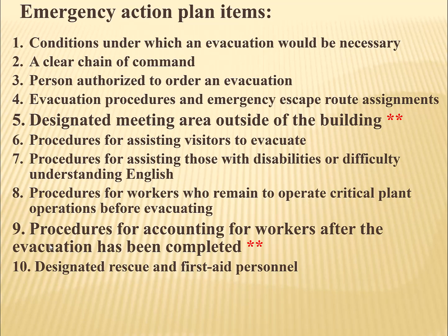What conditions under which an evacuation would be necessary? You have to have a clear chain of command, a person authorized to order an evacuation. And then you have to have evacuation procedures and emergency escape route assignments. And finally, number 5 is the one that I will turn into a testable point. Number 5, you need a designated meeting area outside of the building, outside of the job site area too.